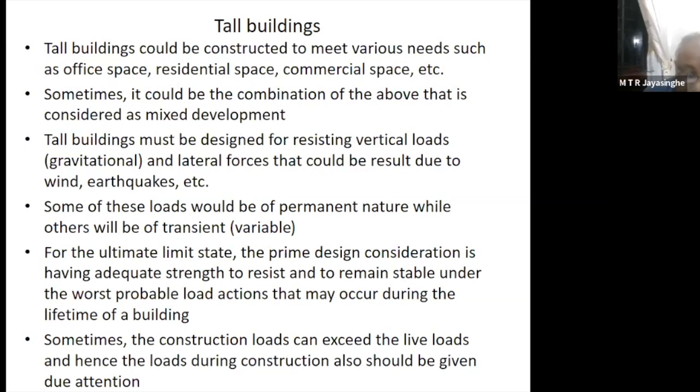So 50% tricalcium silicate will contribute to early strength from day 1 up to 14 days. Beyond 14 days, the strength gain will be lower, but because there is 25% dicalcium silicate, the concrete will continue to gain strength up to 28 days and even beyond.